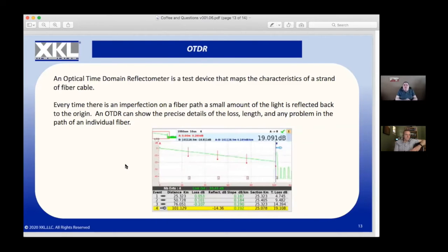There are lots of other technical issues and things to think about with the network. Now, there's a negative loss shown at a splice. Yes. Does this ever make sense? Negative loss. It shows negative. It's just the nature of the OTDR, that when the reflection comes back, it's not truly amplified. I mean, it doesn't get amplified. It's just the nature of the light signal as it's seen. It's not a pure science.